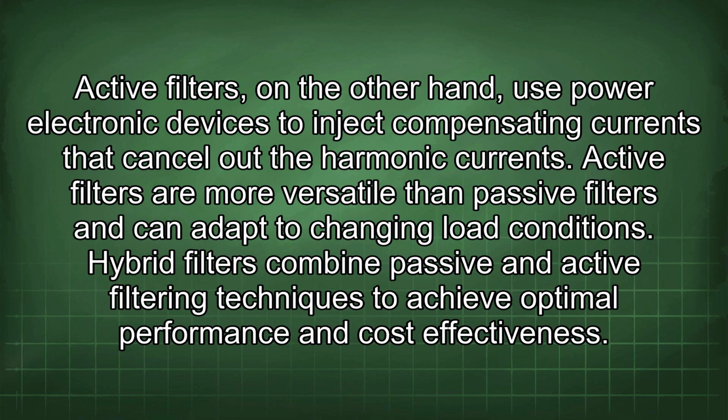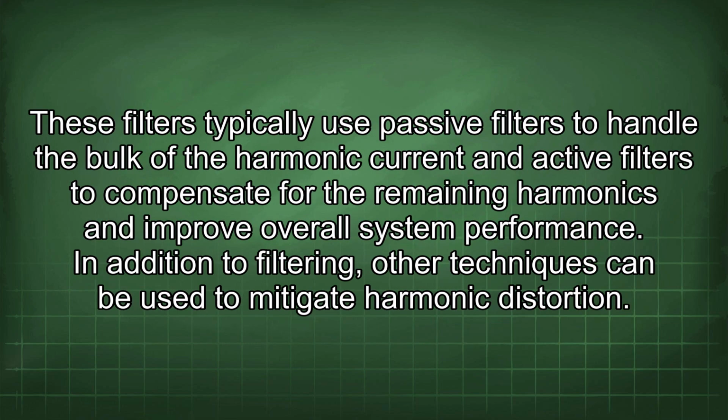Hybrid filters combine passive and active filtering techniques to achieve optimal performance and cost effectiveness. These filters typically use passive filters to handle the bulk of the harmonic current and active filters to compensate for the remaining harmonics and improve overall system performance.